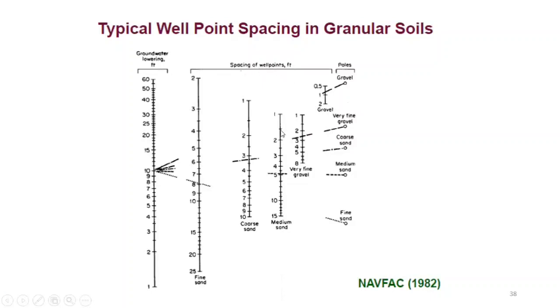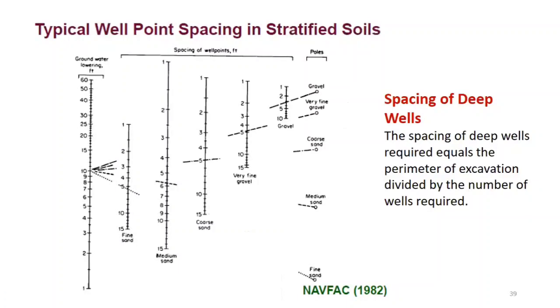In granular soils, similarly in stratified soils, this is how you can use these charts for the spacing of the well points. But there's an example afterwards which I'll show you, where you can make some empirical calculations to calculate the well spacings, and we'll do that in an example.